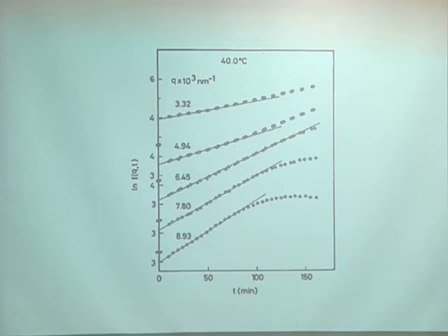And remember I said at the beginning this linear theory of spinodal decomposition depends upon the interaction range between atoms. One of the claims is that this interaction range between atoms is too small for this continuum equation to work at these early times. Because what people see when you do it in metals is you always see the amplitude kind of moving in time rather than being independent of time at a given wave vector. But if anyone would like to do ultra rapid quenches in a synchrotron, maybe we can revisit that problem. But right now, that's kind of the status of the field.